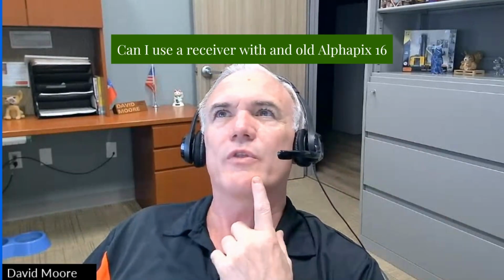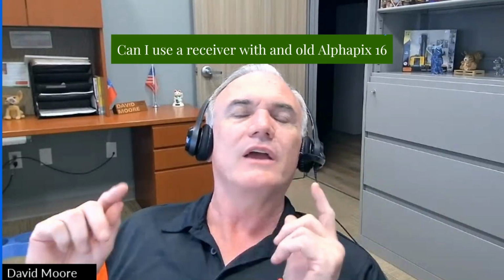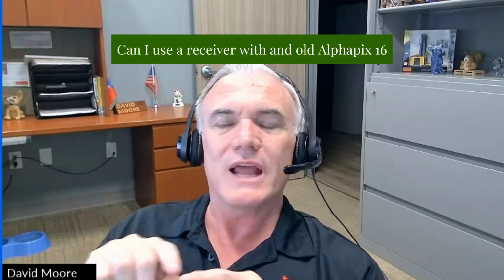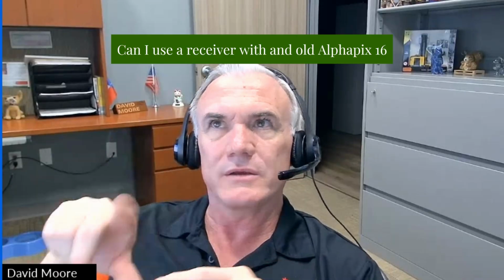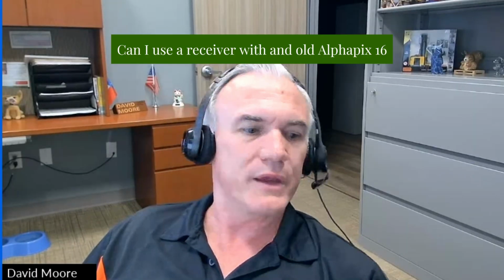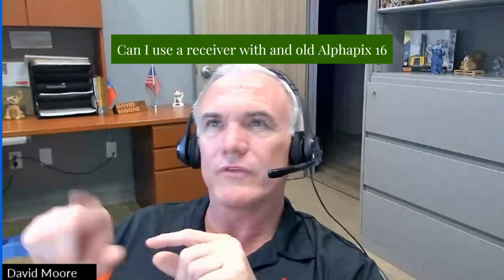Can I use a receiver with an older AlphaPix 16? I assume you're referring to a controller that has AlphaPix 16 Classic. If it doesn't have a network in and out, like an Ethernet switch, no, you cannot use a receiver with that. It only can be used with the AlphaPix Evolution that has the in and out.